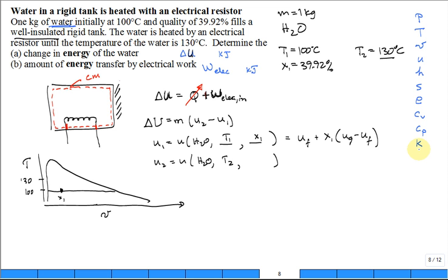And think, do I know the pressure at state 2? Or could I easily calculate it? No. The temperature at state 2, bingo, got one of them. Specific volume at state 2, do I know it or is it easily calculated? And you were helping me, right? Yeah, you were. So why did you say, I can get V2? Why were you saying I can get V2?